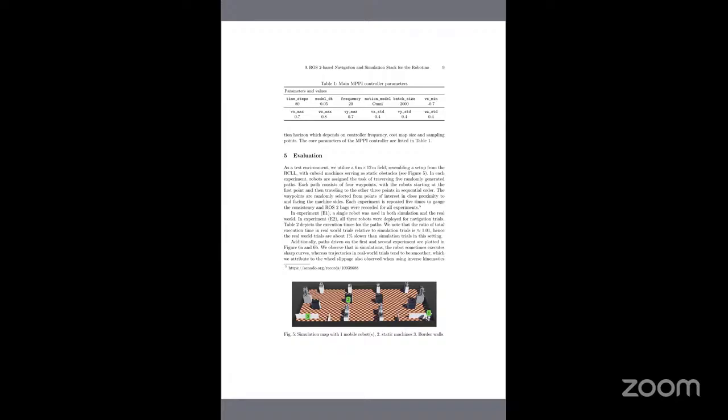So how were these random points selected? The random points were selected where the points are very near to the machines. This is to replicate exact factory navigation. Every experiment they have repeated 5 times to check the consistency. ROS bag recording: for every experiment they have recorded a ROS bag. In the ROS bag: cmd_vel, scan, odometry, TF, IMU, goal poses.